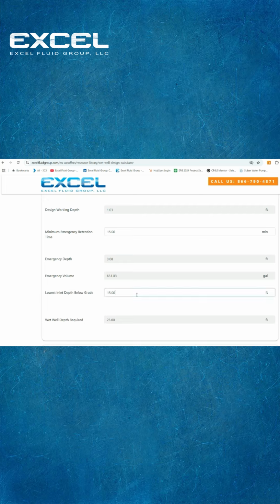Further to that, you would input your invert depth into the wet well, which typically you would find that again on the force main profile drawings. And once you've inputted that, that will calculate your wet well depth for this application.